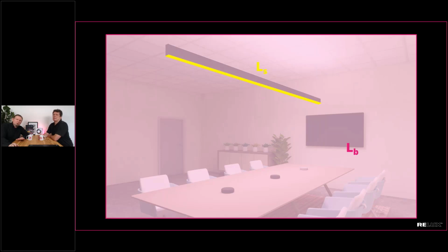And by the way, the background luminance is also the part where we have different values for UGR in different applications, because everybody has slightly different ways to calculate this background luminance. And the last part is the orientation of the observer to the luminaire. So this is the blue part of the formula. This is where we are located in different locations, different viewing angles. You have different UGR values, different glare levels, as you see. So this is, I guess, quite helpful.